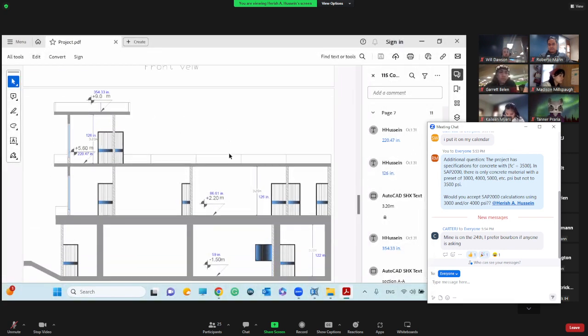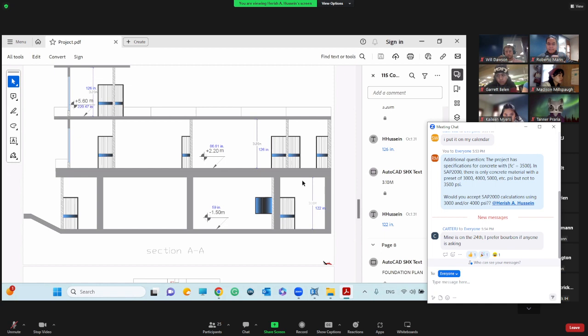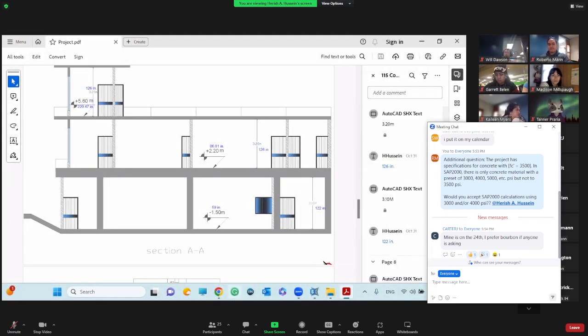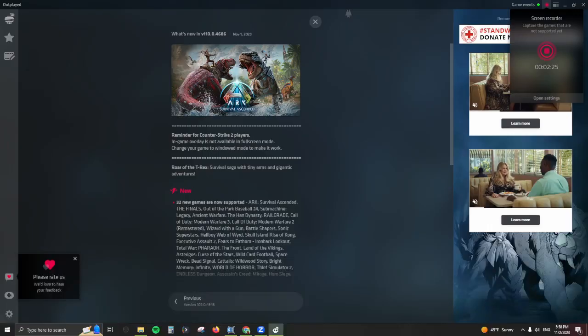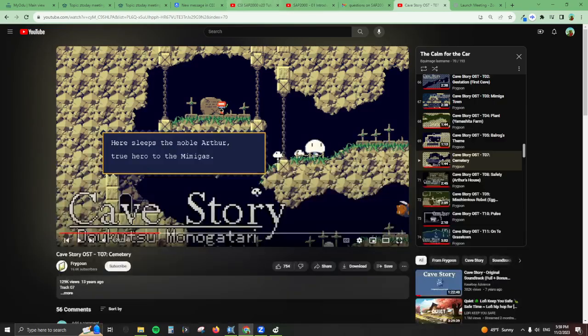That's one thing. And here, this height 310 is 122 plus 15" for the beam. We go to 122 plus around 15. This is just assumption so far. That is 137" height. So that we take this height for both floors. So height is 137". That's for each story.